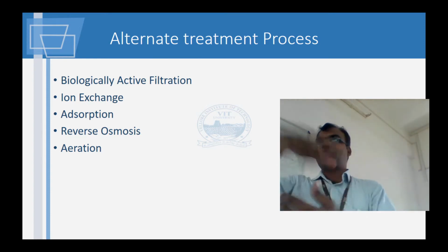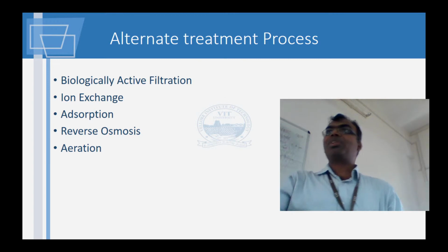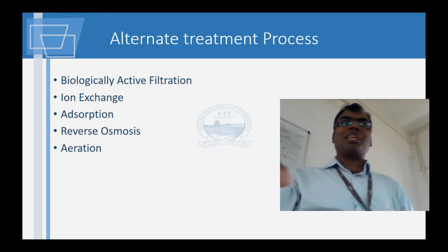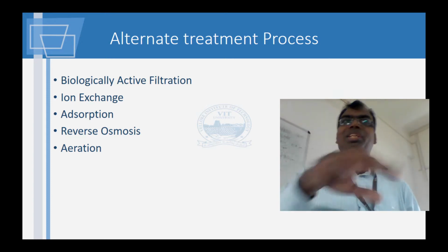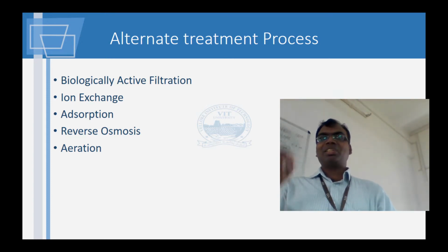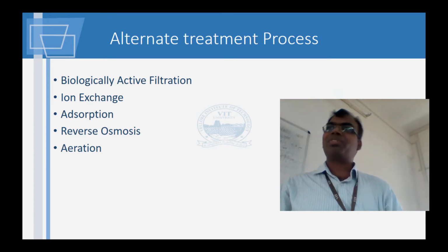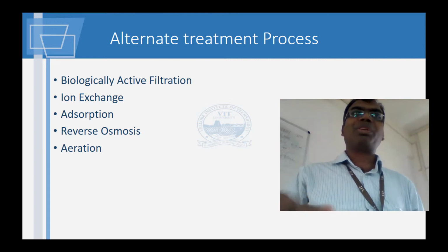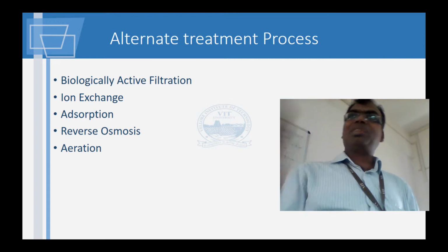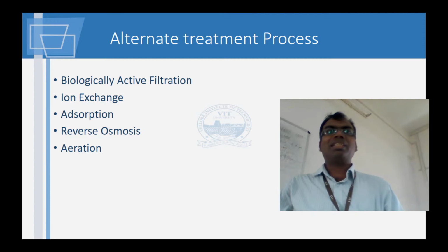So turbidity should be removed by the filter, which is nothing but cloth which is wound tightly. Second is activated carbon. So that should remove also all your coloring agents to a very large extent. Otherwise, the water is very impure, whatever is coming in. And then it goes through the UV chamber.